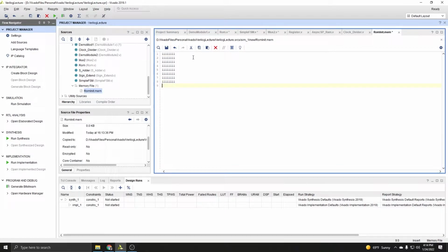And then to be safe, especially in some cases where you have a much larger memory than needed, which you'll have in the case of your data and instruction memories, you can take this and then just add a bunch of 0 lines afterwards to make sure that even if you don't occupy every space, the rest of them get initialized with 0, so you don't ever accidentally get an X of some sort.